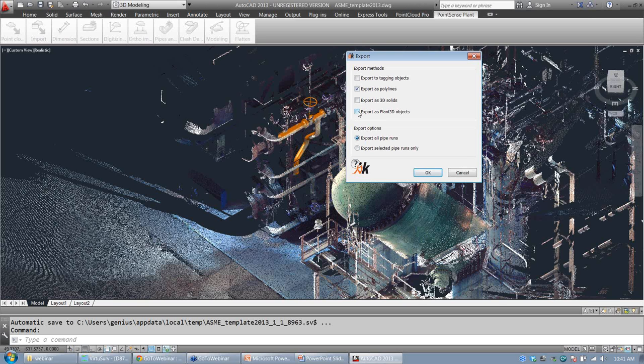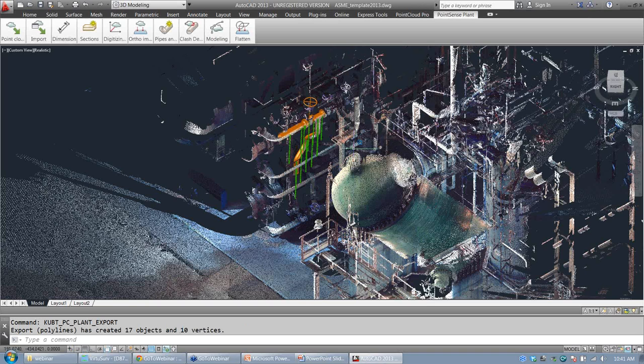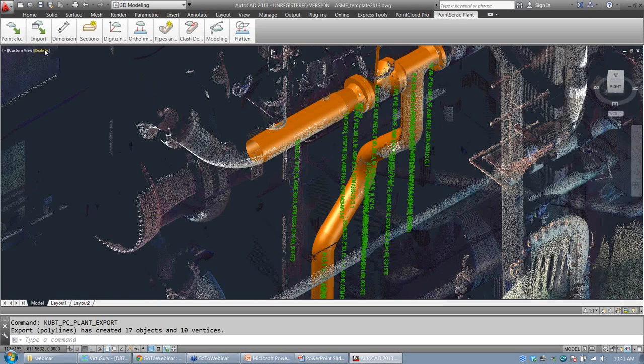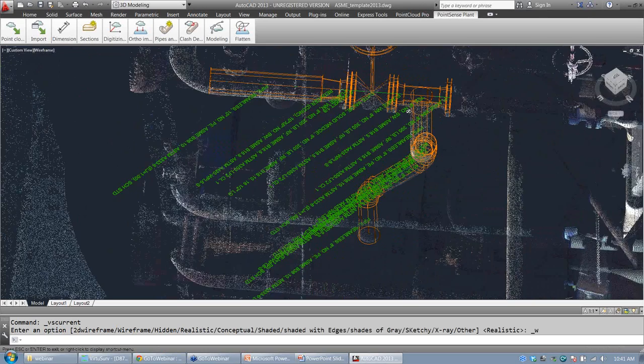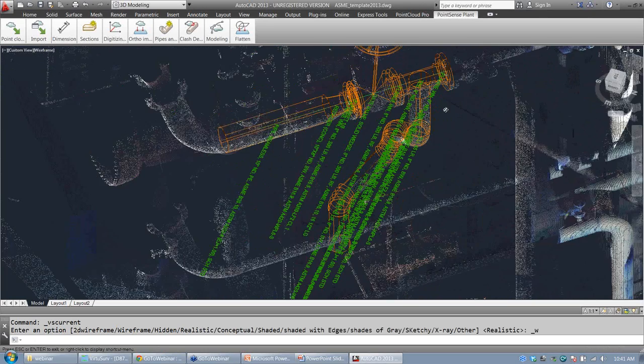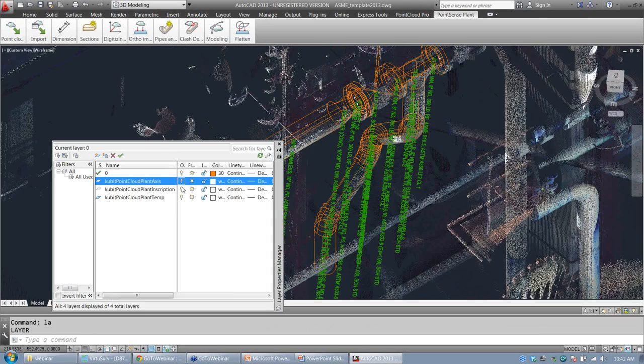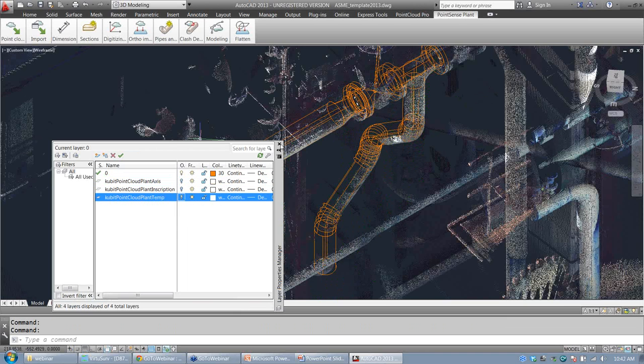We'll actually be going through this stuff more later, not in this webinar so much. We would love for all of the beta testers that are using Plant 3D to use this option as much as possible. We want to make sure it's perfect for release. For the center line, though, I'll just hit OK here. And it'll actually do two things. It's going to label all the objects, and it's actually going to create a center line as well. It's fairly hard to see, but if you can see that green line behind there, that gives you the start, center, and end points for all the key objects. And it is actually on its own layer, so you can choose whether to leave it on or turn it off.